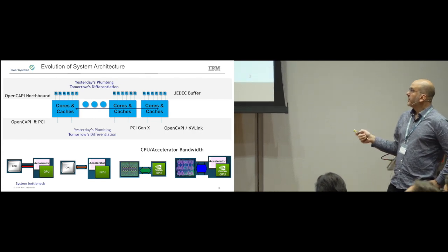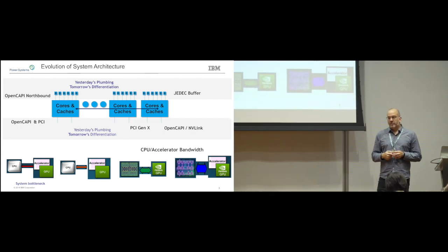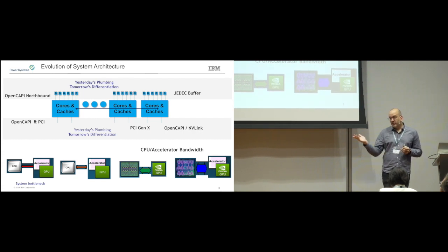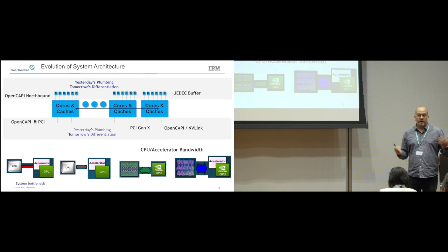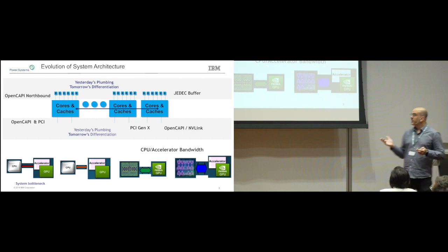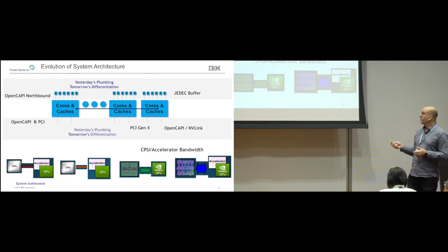The other side of things is I/O. I actually think PCIe is a pretty good standard compared to even previous PCIe. The switches are pretty good, and so are the high frequency SerDes. They're good interfaces for connectivity, especially for lower or higher latency devices. If your device is in the many tens to 100 microseconds, or 10 microseconds, PCIe is reasonably good at transferring to those. But PCIe is really centered around DMA transfers. There's quite a bit of latency in the path, and it's not designed to be tightly coupled to the device. So how we like to differentiate is by doing things better than PCIe.